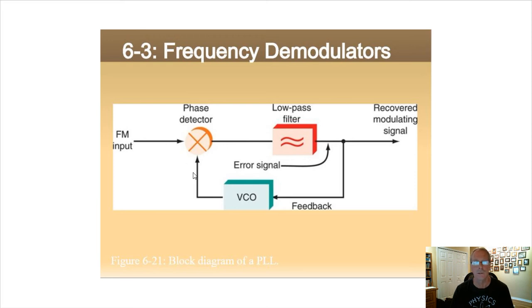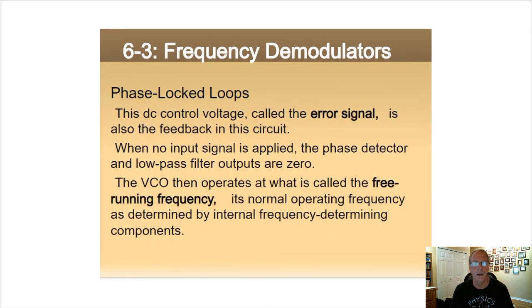They're the same frequency. So all it has to do is wiggle the VCO a little bit just to slide the two inputs so that they're 90 degrees apart. You would have seen this in the lab. It's a great demonstration on a two-channel scope. I'm kind of bummed that we didn't do this, but you can draw a picture in your mind of it, hopefully. So anyway, that's the free running frequency.